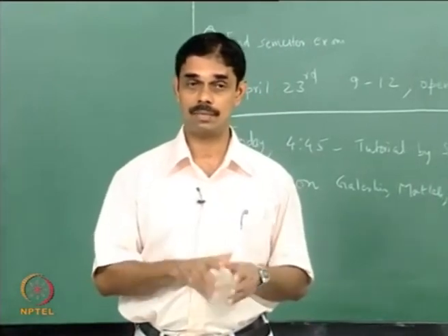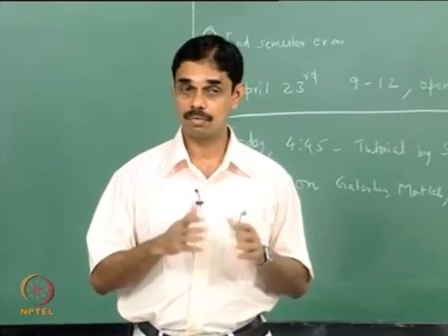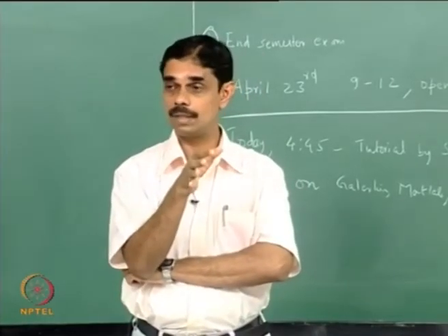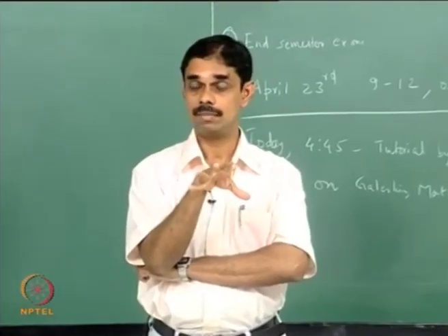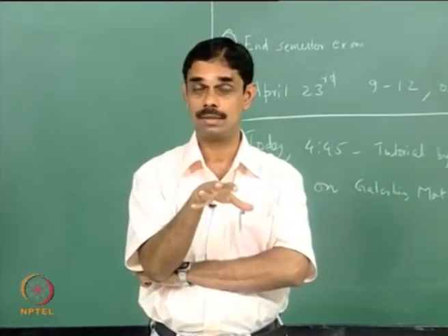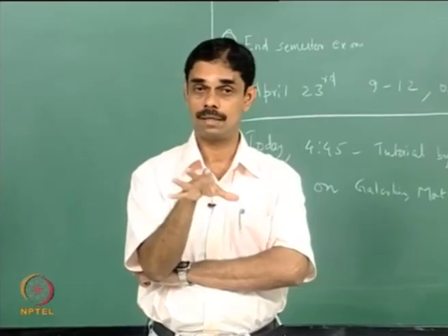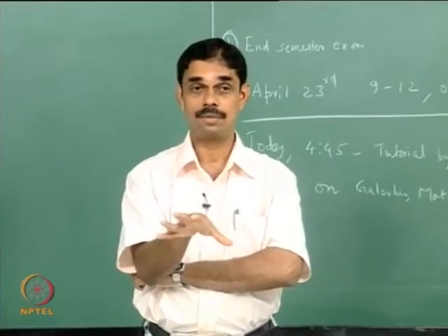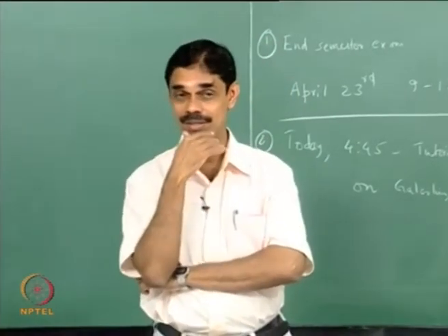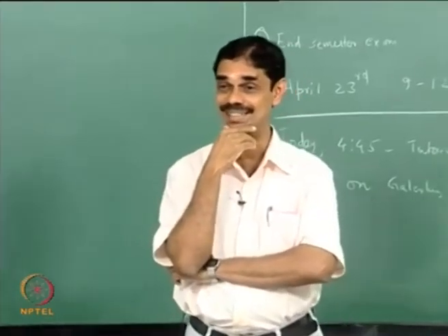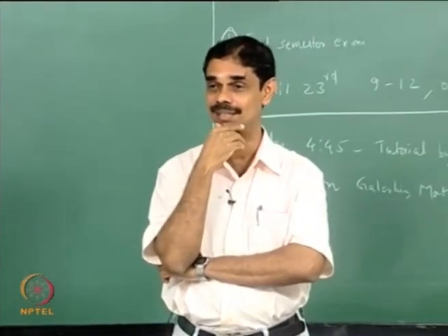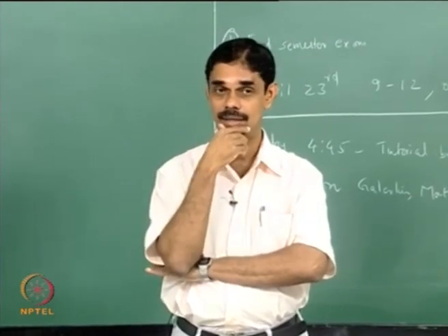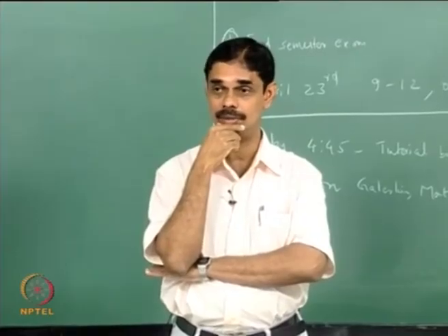Now, why would NOx be low when temperature is low? Nitrogen won't react. Yeah, at low temperature the NOx production is less, so at least one of the ways of producing NOx is less. So people have understood that if you lower the temperature of the combustion, you will have less NOx. So wonderful, you proclaim that you have solved all the problems of the nitric acid and so on, keep all the environmental activists and left wingers happy, and then you make these combustors, and then some unintended consequence happens. What would that be?